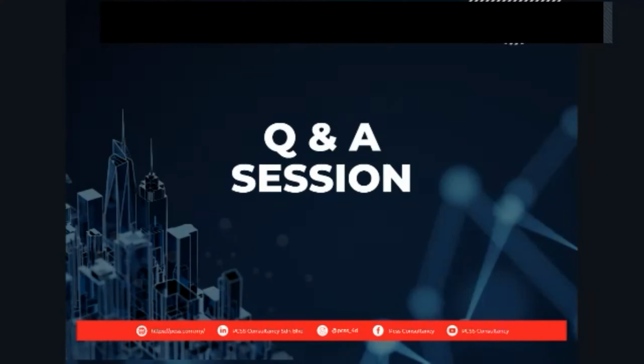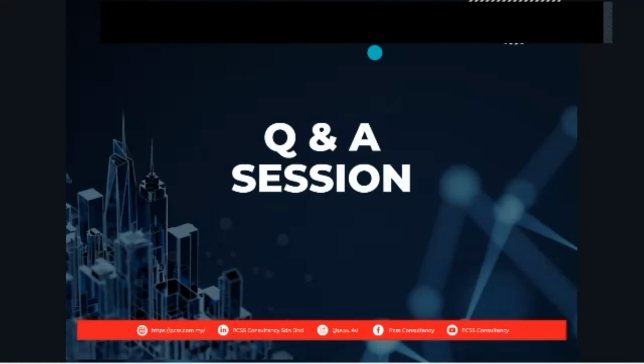I just want to add a little bit more to the first question. Does BIM execute plan, maybe you're talking about the BEP, require shop drawings? It depends on the stage of the BIM where your BEP is written. If it is shop drawing, it is construction stage. Usually the BIM execution plan will be written from the very beginning and revised along the project life cycle. So you will have at least three phases: design, construction, and handover, at least three revisions of the execution plan. So the answer to your question is, yes, if it is in the construction stage, you will need that shop drawing submission.